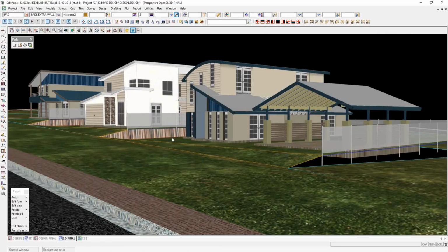So you want to be able to see this retaining wall between the two pads, and then see it come out to the footpath, and then be able to model this pad here, going from an upward slope to a downward slope and transitioning to match into the footpath nicely. So you also want to be able to check using 2-point cross sections and things like that, profiles, sections through here to see that your driveway will get out, and that for drainage of the pad and so forth. So that's what we're going to look at the moment.